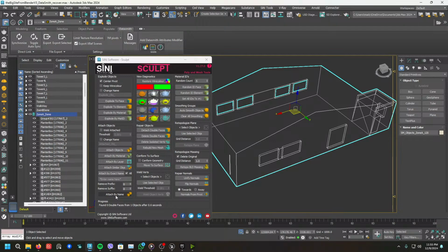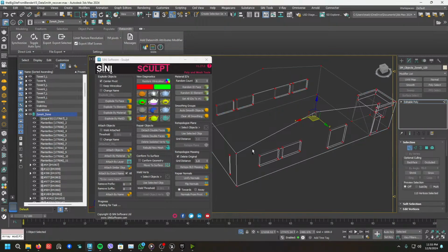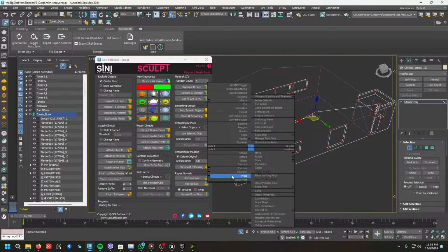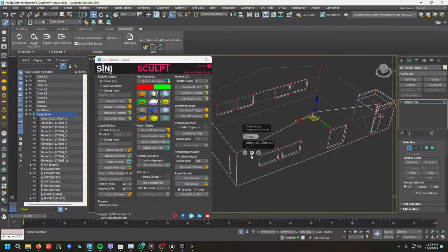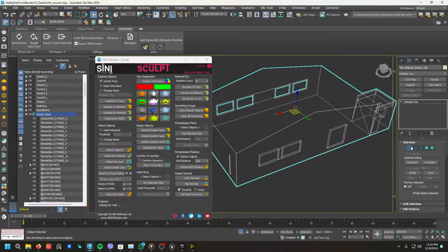You can merge two vertices that are not connected. Vertices that are not connected will give bad performance in Unreal Engine. You need to be careful. Also for these tools we have merge vertices. Usually what I do is create a weld vertices modifier, give some distance and do it like this to be sure.